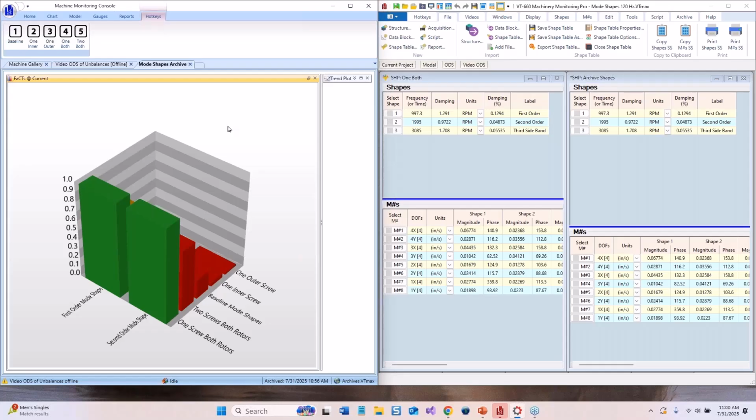The video only captures 2D motion, so if the primary deflection of the mode shape is in the direction of the recording, in other words, in and out of the field of view of the cell phone, then you need to get one from a right angle. Then comparing a like point and doing ODS-FRFs and so forth, we can actually merge all that data together and get 3D motion. So that's a coming topic also.